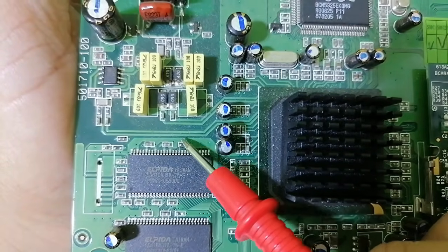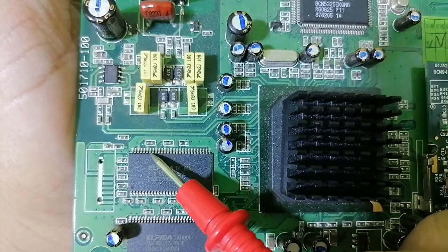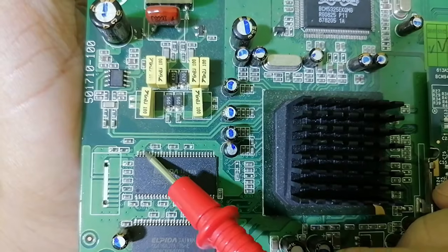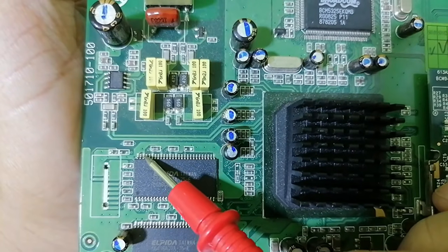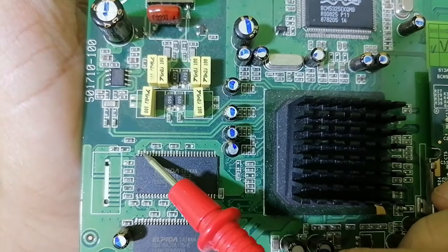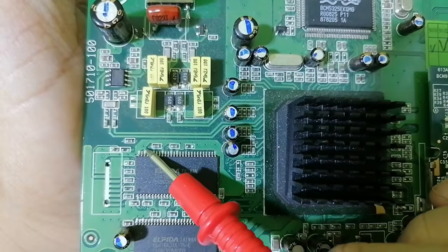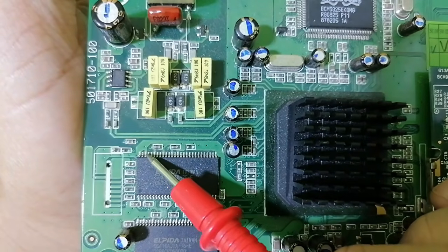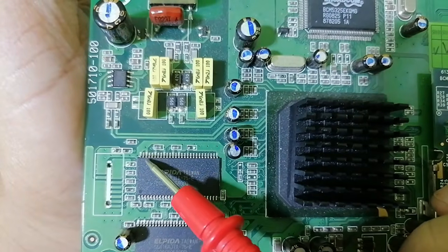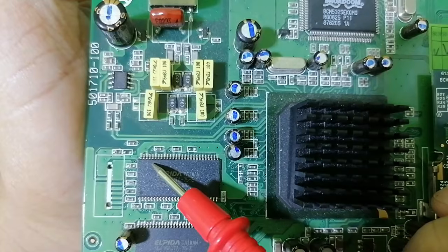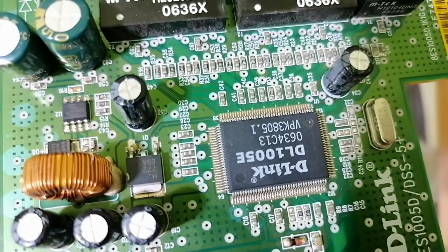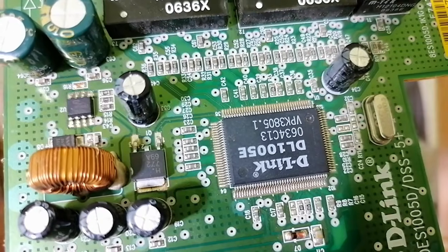So the ground is connected to the IC in this pin. In this pin also, as you can see, all these are ground. And in this pin also we have ground. This is basically ground. If I put one probe of the multimeter here and another probe in the ground, I will get a buzzer, a continuity. Okay, so this is how I can know whether the pin is connected to the ground or to a power rail or is just an enable signal. So guys, if you understand this trick, you can analyze any circuit or IC.